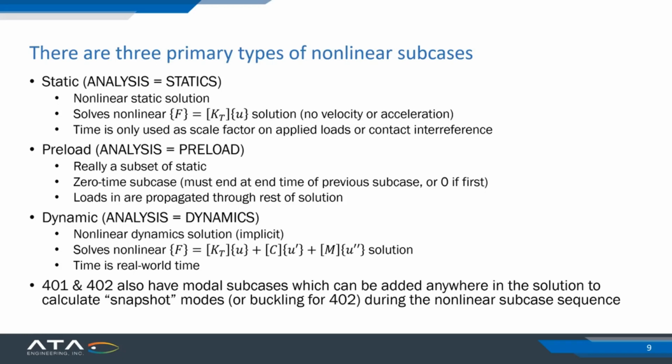Next is the preload type subcase, and you can actually think of the preload type subcase as a subset of the static type subcase, because it basically is a static subcase, except it occurs over 0 time. And the reason it exists is because when you have a preload type subcase, any loads that you have applied in that preload type subcase are automatically propagated throughout future subcases without you having to carry those load statements through them.